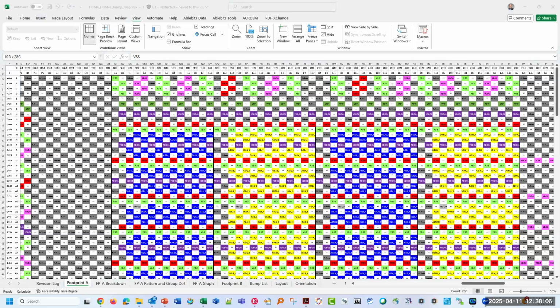So basically what they do is, based on the inaccuracies in die placement, rotational accuracy or translational accuracy, they actually on the fly, based on the placement of the die, readjust the routing layer to make sure that the connectivity is matched, right? They do inline scanning, look at the scan result, and adjust the substrate routing.